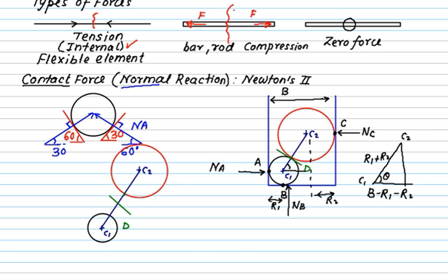Now what will this top cylinder do? The top cylinder will show here. So what exactly we are doing in the FBD, we are showing the presence of this body over this body, but at the same time we are hiding the body. That is what is called a free body diagram. The body is isolated from the rest of the world, but you can visualize its effect.